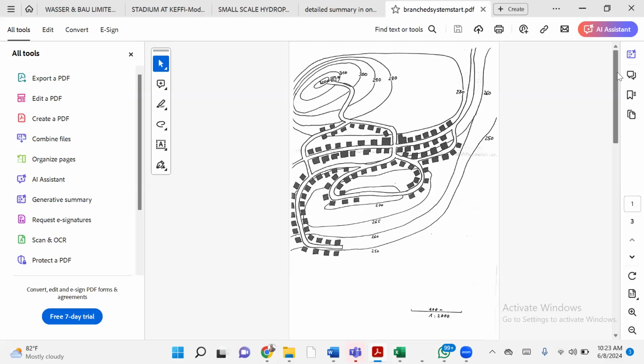Now, the distribution network is what you're going to design, because the transmission network is very simple. Based on the water requirement, your tank size, and then the rate of extraction, of course, you cannot extract more than the recharge rate of the aquifer. And in terms of surface water, you cannot supply more than the production rates of the water treatment plants. So that one is fixed, it's simple. Based on your population equivalent, you know the daily requirement. We did all that last week.